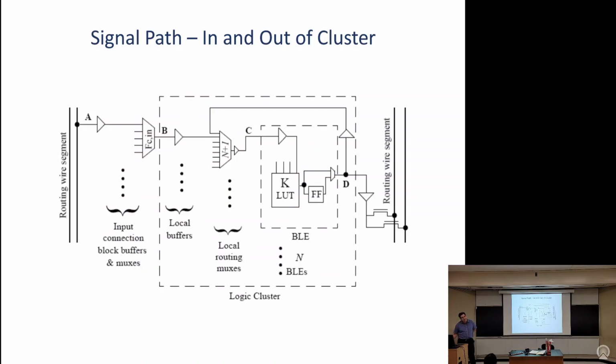In direct drive routing, you basically change this to MUXes, and you would have all of your MUXing done with pass transistors on this side of the buffer. So it's a good idea. We're going to get to a paper that shows that's a good idea. That wasn't known to be a good idea at that time, okay?